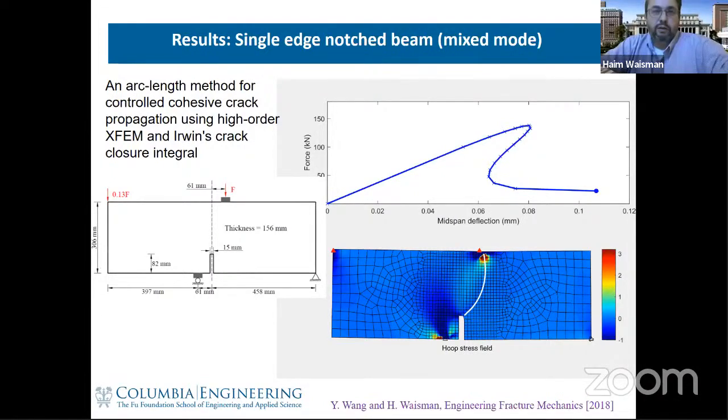So this is a good point, but the problem with this is that sometimes I have damage that is, I don't know, 0.5, right? So what would be exactly, you cannot directly correlate the amount of damage with the amount of the thermal conductivity that you have. It's not a linear connection between them, right? It's a nonlinear kind of, you saw that the homogenization is a nonlinear process. It's not just a simple linear ratio 1-to-1. Okay.